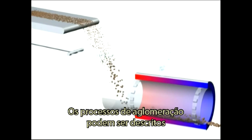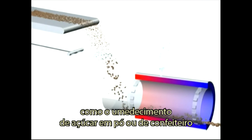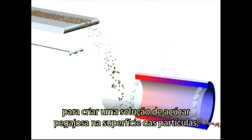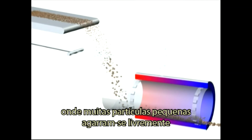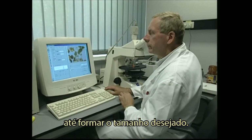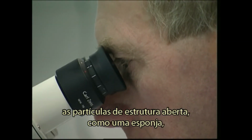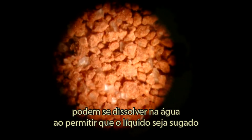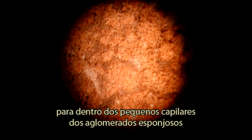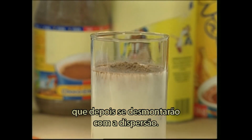The agglomeration process can be described as the wetting of powdered or icing sugar to create a sticky sugar solution on the surfaces of the particles, where many small particles cling loosely together to a desired size. If the degree of agglomeration is sufficient, the open, structured, sponge-like particles are able to disperse in water by allowing the liquid to be sucked into the small capillaries of the sponge-like agglomerates that then fall apart upon dispersion.